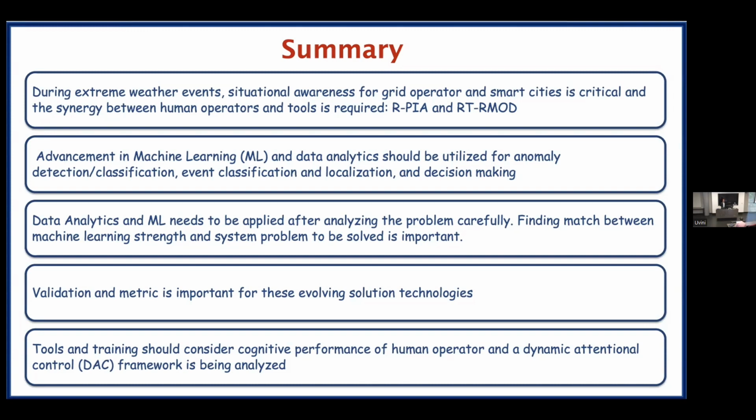Because now we can, especially if DER is grid forming, we can even make a smaller system with grid forming taking the lead, even without macrogrid, if you have a controller, right? So we can make an island with grid forming inverters and controller to operate as a macrogrid without macrogrid controller, right? So all these possibilities exist, and possibility typically means more number of control variables with more flexibility, which becomes more difficult to solve.